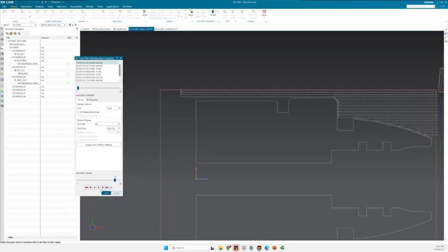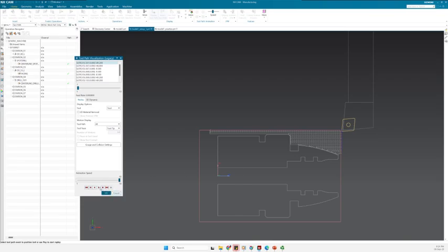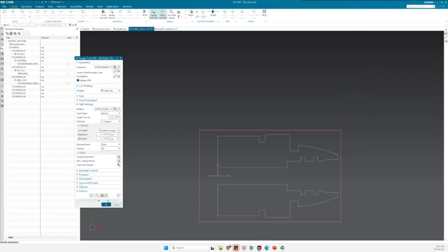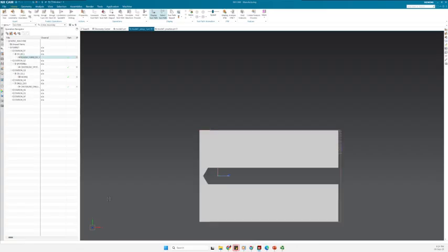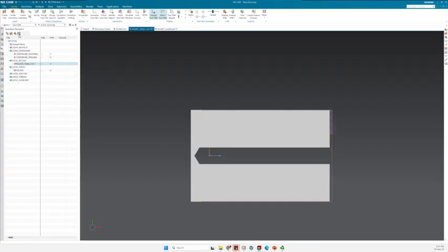Again, generate and verify. So I don't play it now. I just do it this way so that it just goes to the end and it looks okay. All right, that was it. And now what we need to do is quickly check that this roughing outside diameter is there, and we are good to go. We're gonna go to the grooving, and then after that, I'm going to pause again and go into the next operation, and you can replay to your cases as well.